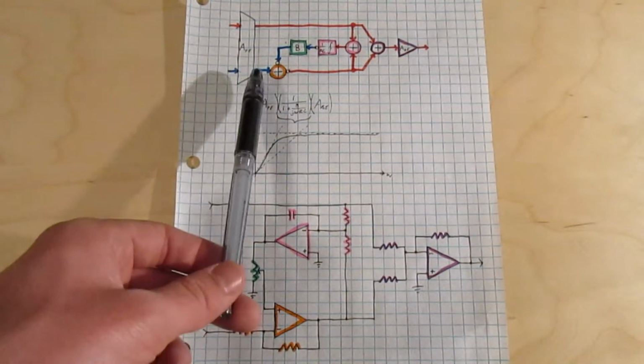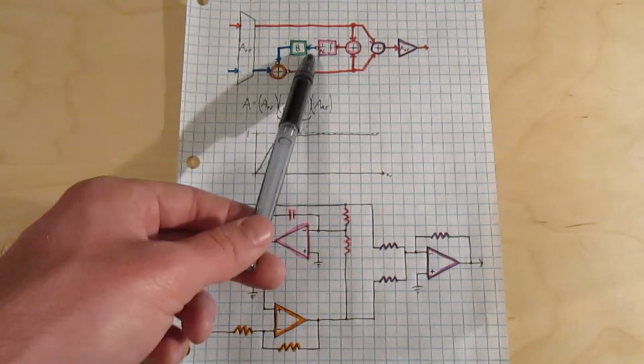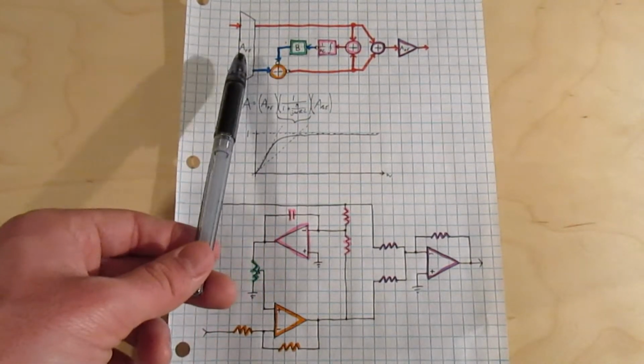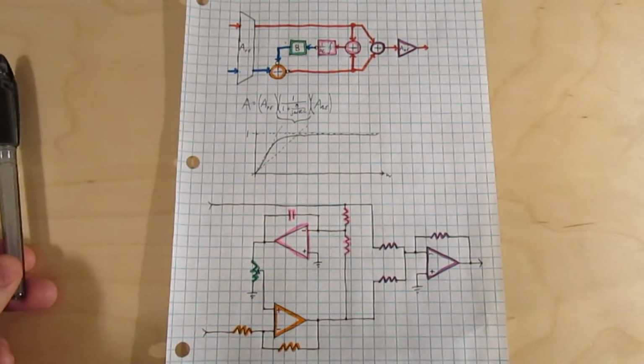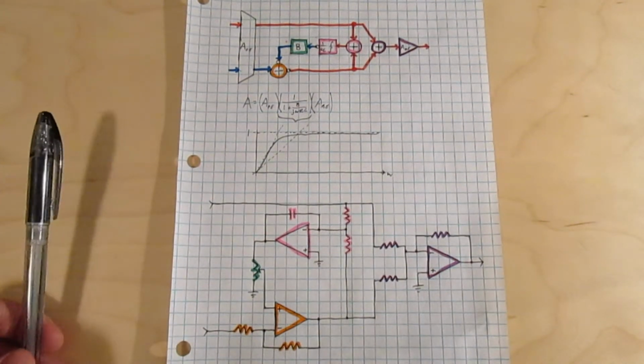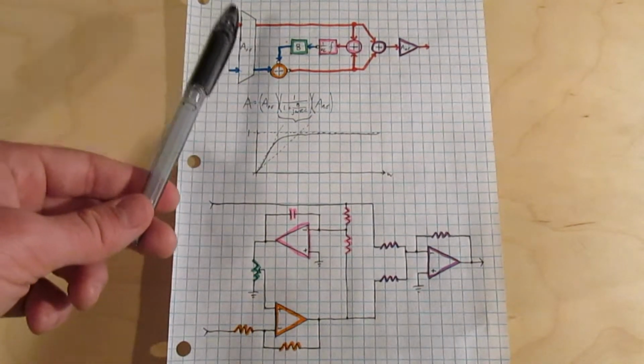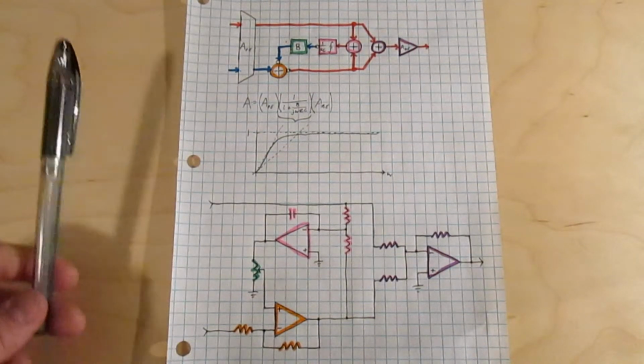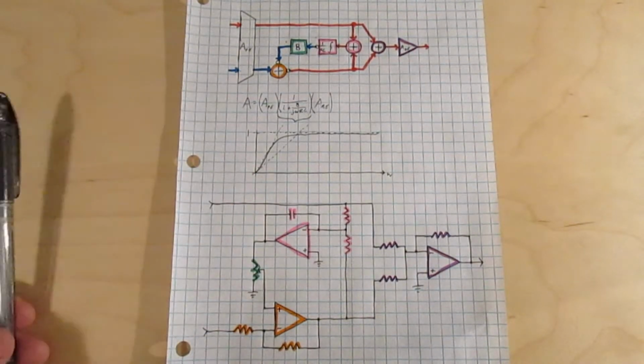In order to make sure I don't have too much DC offset at the input of the DC offset tracker, I would need to reduce the gain of the front end by a factor of 2. So then I'd be in the same situation that I was in with the last circuit, with the common mode gain reduced by a factor of 2, and then the common mode rejection was made worse.